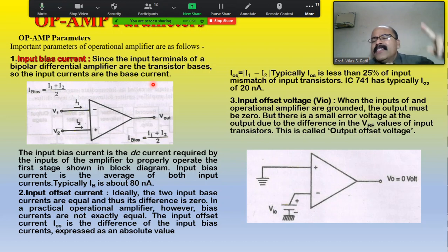We know that. Just the designing details of the operational amplifier. There are two transistors Q1 and Q2, which are a Darlington pair of each other, and at the bases of the two transistors we are applying the voltages V1 and V2. After applying the voltages V1 and V2, the base currents IB1 and IB2, or I1 and I2, will flow through the bases, and that base current will be amplified at the collector, because it is the common emitter mode of the amplifier.